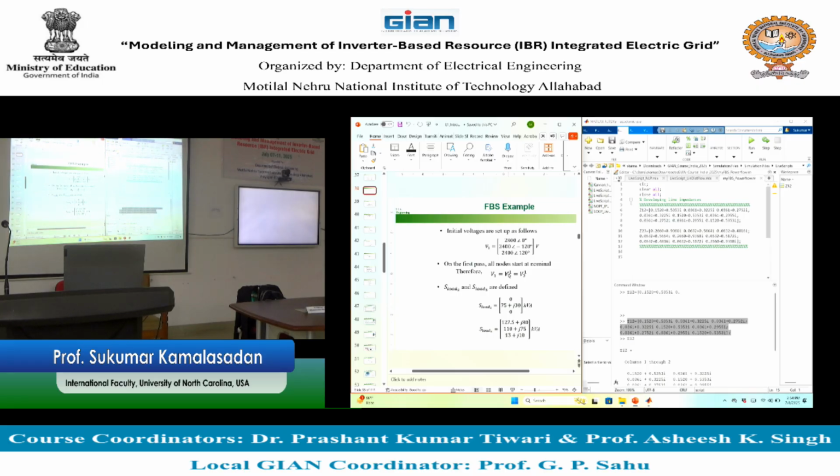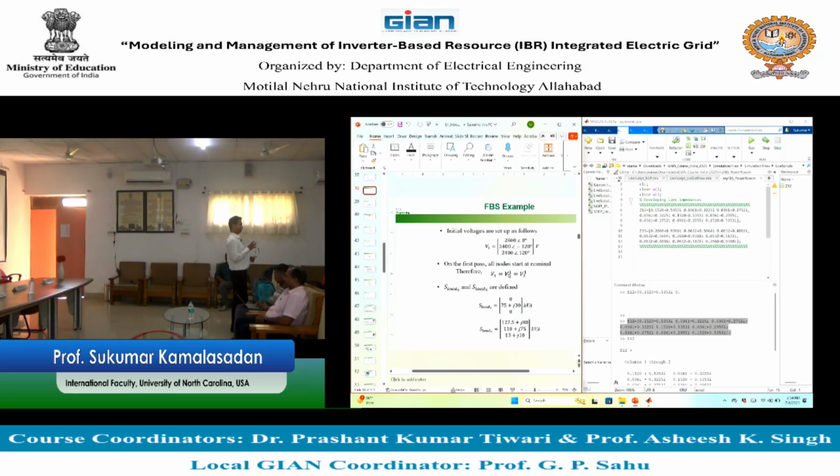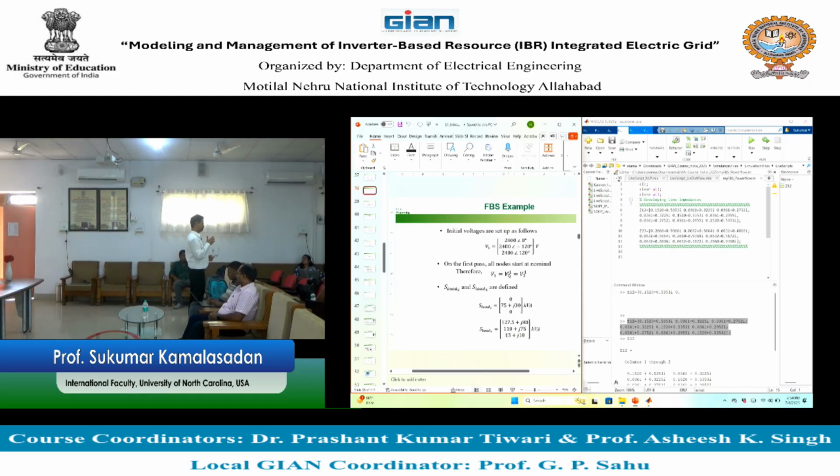So what we did was we said 2400 angle zero is the voltage on all the buses. So all that is actually our guess, right? I mean, we know it's not true. So you are putting in V1, V2 1 and V3 1. That V2 1 is 2400 angle zero, right? So V2 2 is the new one that you calculate. So you get an error between V2 2 and V2 1, which was 2400 angle zero.